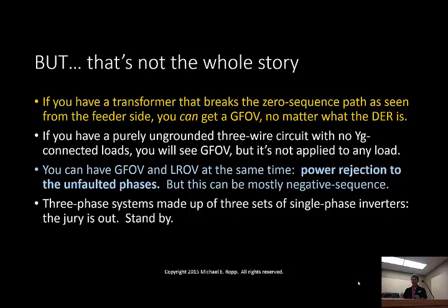So the inverter's controls are going to say, what's happening is I've still got power moving in from the DC side that now cannot go out on the AC side. So the DC link voltage, that capacitor on the DC side, that voltage starts to shoot up. The inverter regulating controls are going to say, ooh, problem, open the throttle. Try to get that power out, try to keep the constant power aspect going.